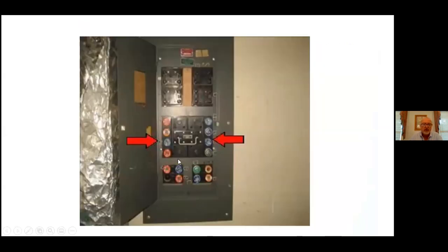Here we're looking at our fuses again. These arrows were showing that the fuses were blown. This one in the center is the main disconnect in this older fuse panel. By pulling this one out, you would have 2 very large tubular fuses behind that disconnect, and that would cut the power to the home.